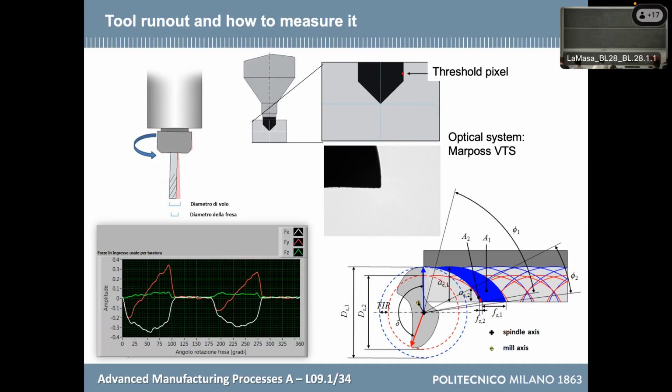With this situation, the cutting edge which is more exposed is removing much more material, and the other is removing just a tiny portion, which means that the action of the mill is not balanced. When it is the turn of this cutter, my mill will feel more force and will bend more, and in the other case it bends less. Not only does it bend, but maybe I break it, because I didn't select the parameters for such a big chip thickness, but it is happening because of the run out.